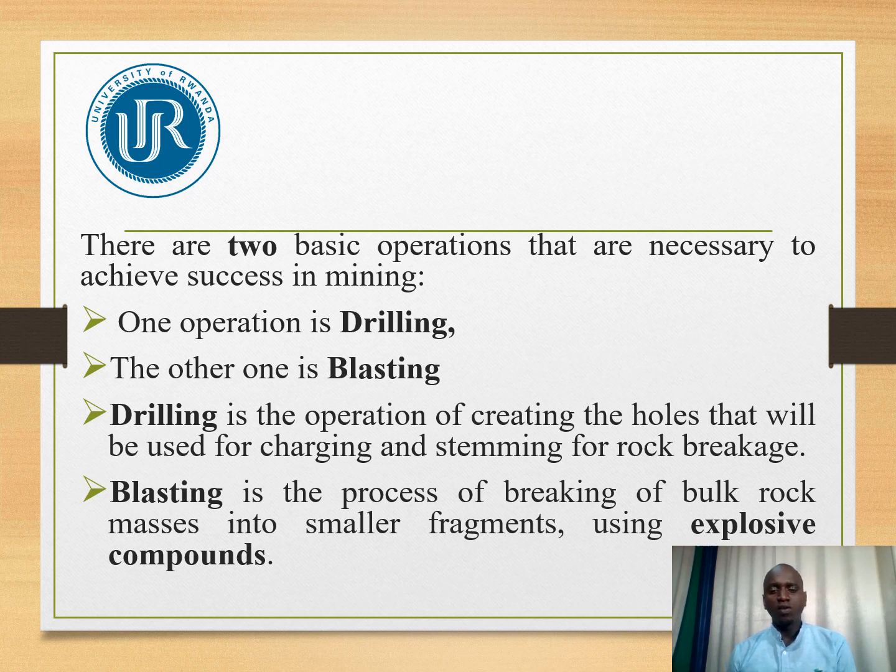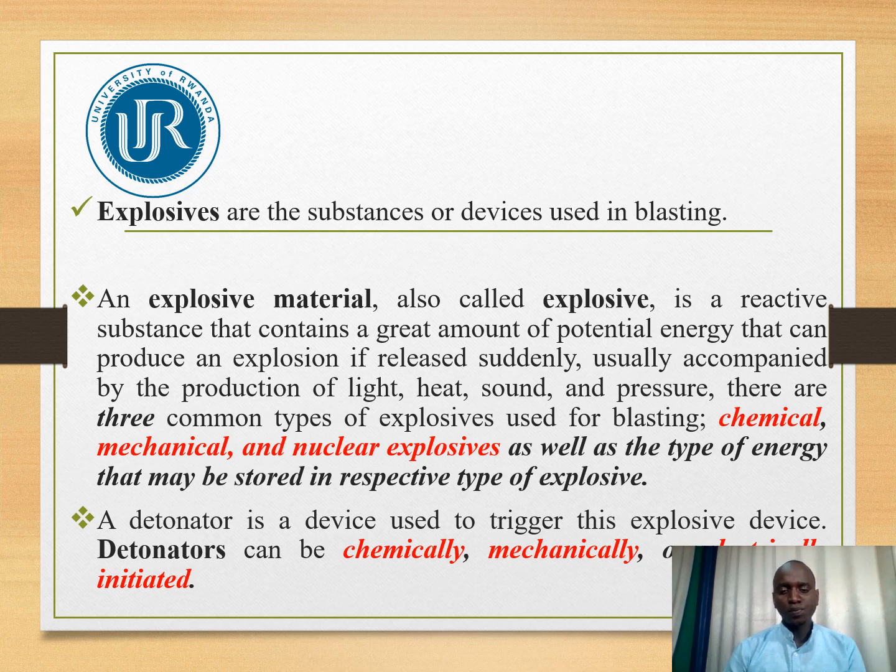So there are two basic operations that are necessary to achieve success in mining. One is drilling, the second one is blasting. Drilling is the operation of creating the blast holes that will be used specifically for charging and stemming for the local breakage. Blasting is a process of breaking the rock mass into small fragments using explosive compounds. And explosives are the chemical substances or devices used in blasting.